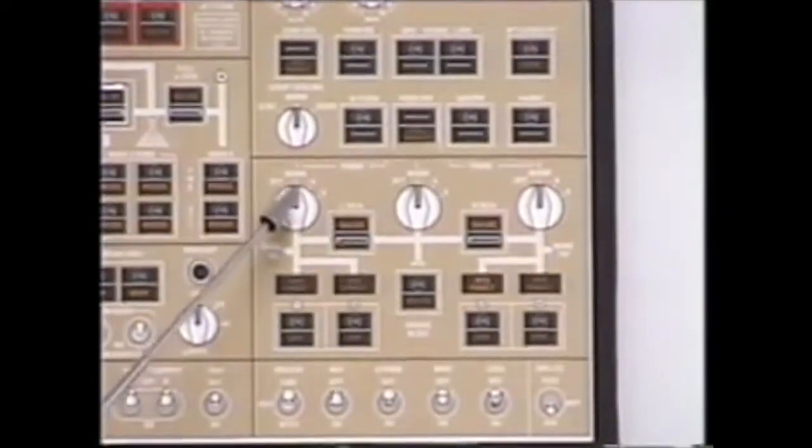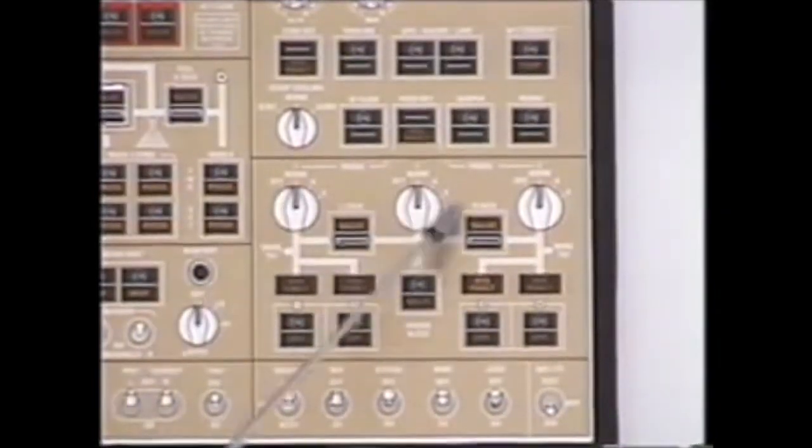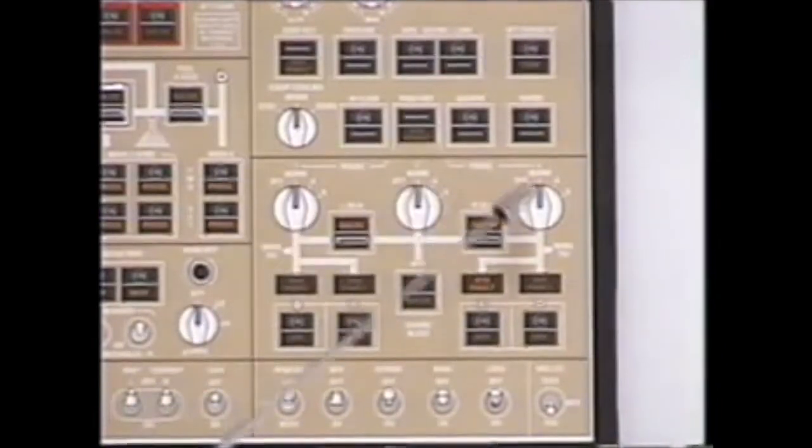Continuing up, we have 3 air conditioning packs, number 1, number 2, and number 3 pack. All 3 packs put out the same temperature. That temperature is determined by the coldest zone. There's no sense having the packs work harder than what they need to. So the packs put out the temperature called for by your controlling zone, or coolest zone. All 3 packs put air into one manifold. So it's not which pack you turn on to cool the flight deck the best, it's the number of packs that increases the flow.